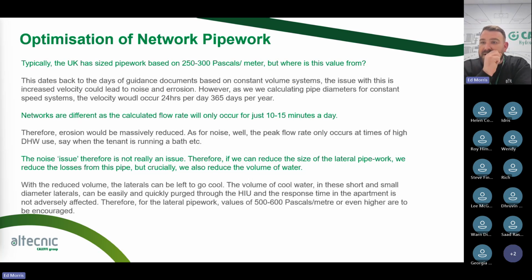Are there any specific considerations for retrofits or upgrades to existing central plant when incorporating HIUs, and how can potential challenges be addressed? Retrofit is a massive market now for district heating, and we have to make sure that the system is fit for the use of HIUs, which is really important. You cannot necessarily just adopt the existing system. Make sure, again, your pipework sizing is right. You've got to get the velocities right. You've got to get your flow rates right. You've got to get your sizing right and your heat counts right.